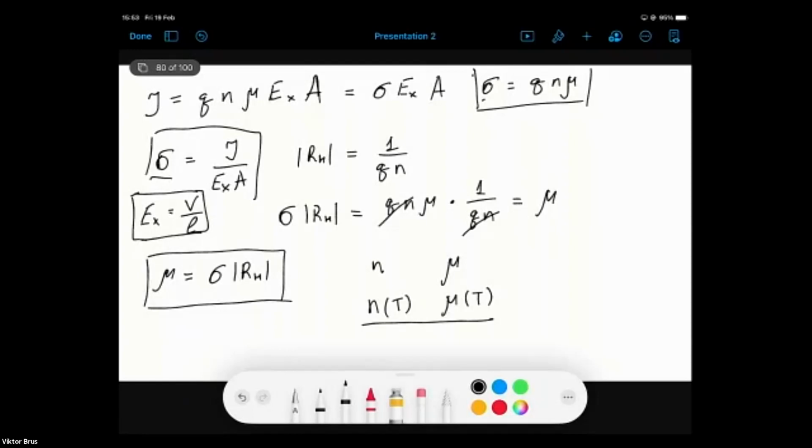And besides the scientific value of this phenomenon, it also found a practical application in so-called Hall sensors, for instance, and they are used in cars to monitor the position of shafts and calculate the moment when to provide electric discharge to ignite the mixture of gas and air, and there can also be a much broader field of application of this type of sensors.